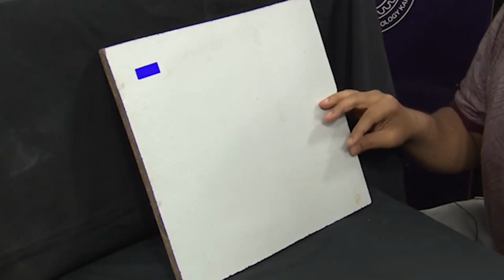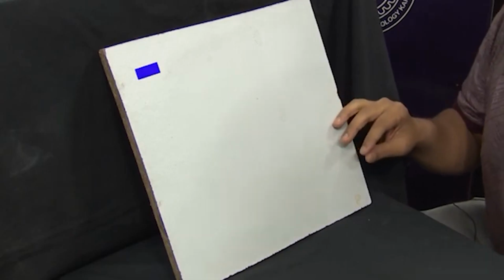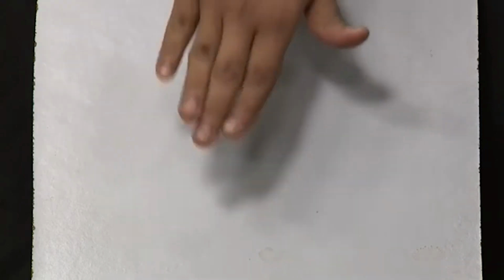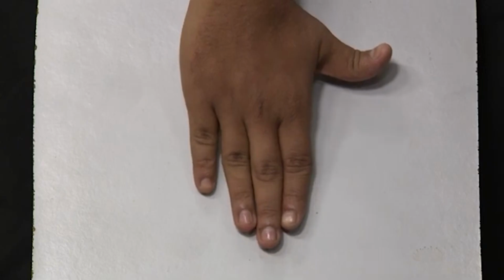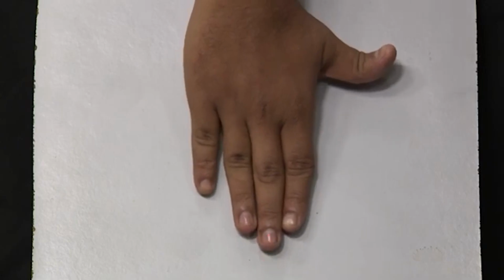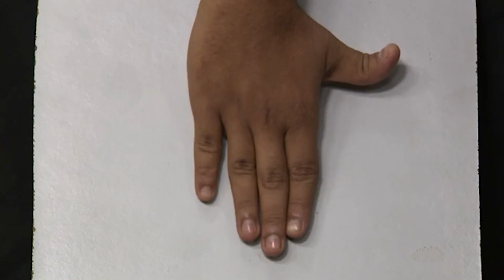Let us consider this white board as a planar structural feature in the deformed rock. Now we will measure the attitude of strike and dip of this planar feature. We will follow the convention of right hand rule. The convention of right hand rule goes in this way: we will place our hand over the plane and our index finger will point down dip direction and our thumb will point towards certain direction.